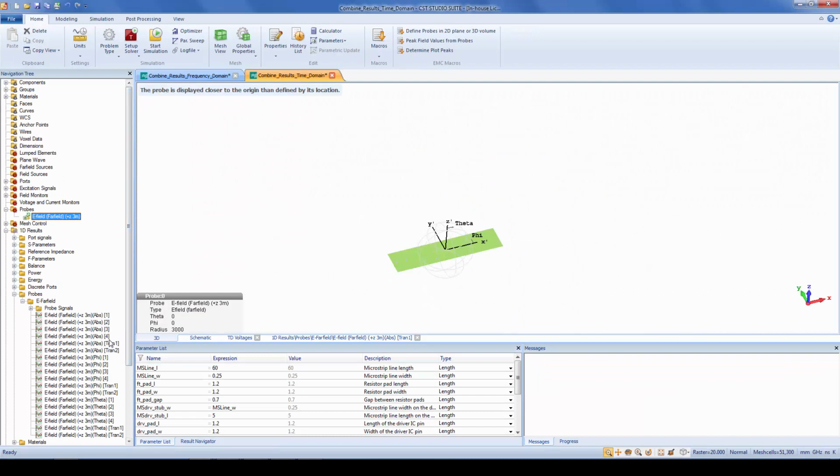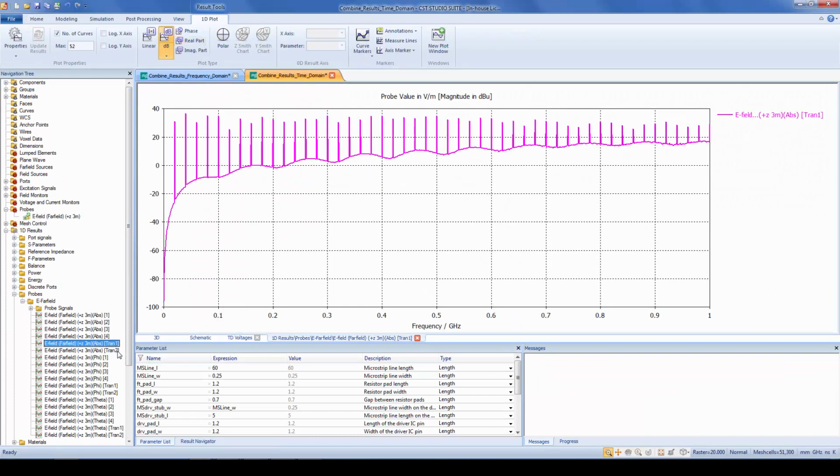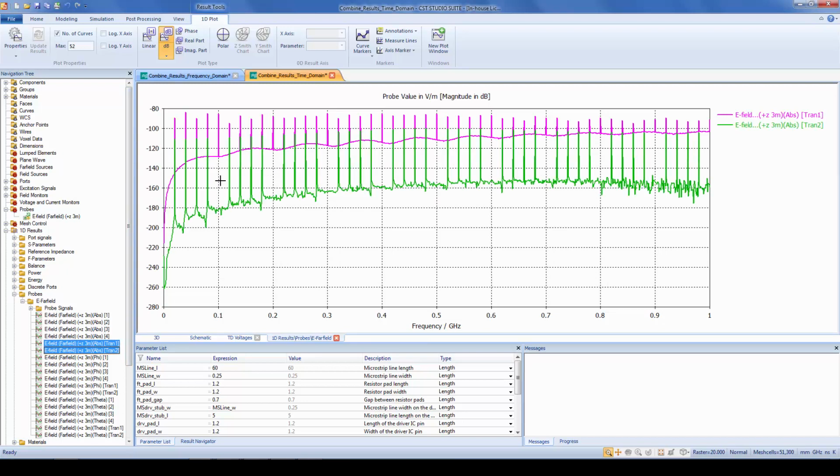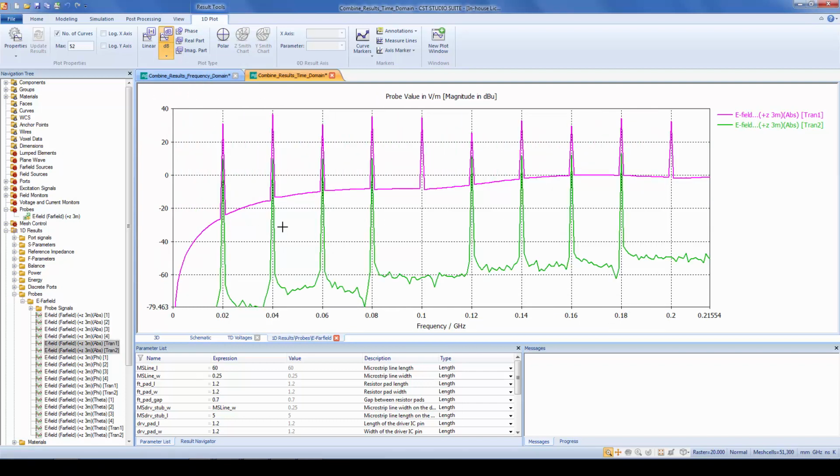This is tran 1 when the diode was included, and this is tran 2 where the diode is removed. And you can see that the diode has a pretty significant effect there, of course, because the complete current path has been completely changed by adding the diode. You can also see that certain frequencies that were included in the spectrum while the diode was included are completely gone when the diode has been removed. This is something you would expect.